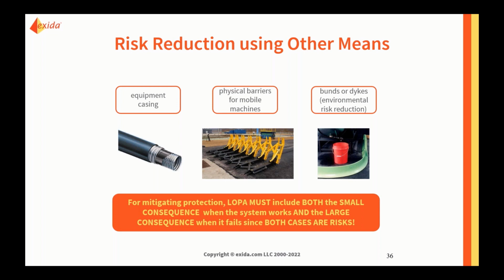Now, I've gotten another question that is also probably worth clarifying at this point. Now, I'm sorry, let me read this directly. A BPCS is demanded continuously, so it is like the brake. So for the initiating event control loop failure, yes, that control loop is operating in high demand, and it may or may not be a safety function. And what that means is that whether or not it's a safety function or not, as the initiating event, it needs to be treated as an initiating event frequency in our overall risk analysis of the situation.